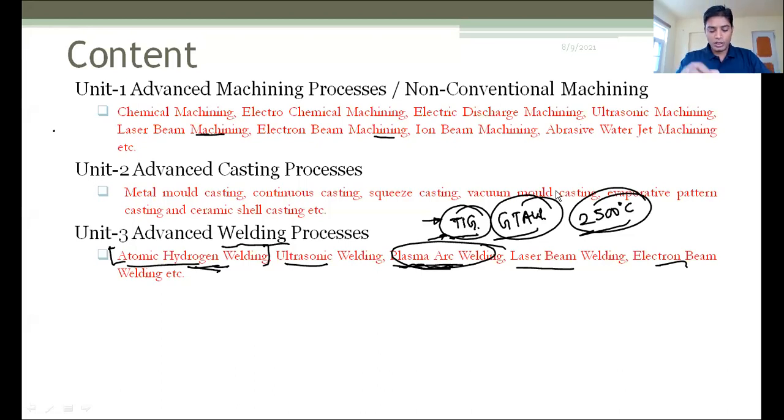So machining is done on a single workpiece with a tool, or in EBM, by bombarding electrons over the workpiece surface, which removes the material. But for example, if there are two different materials and we bombard at the edge between the two, then material will be removed from this area.